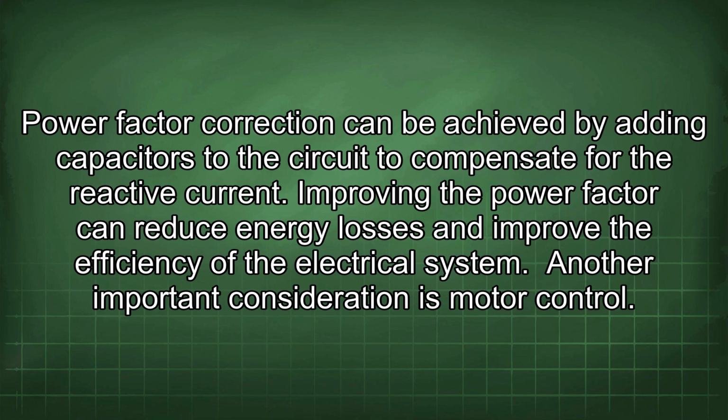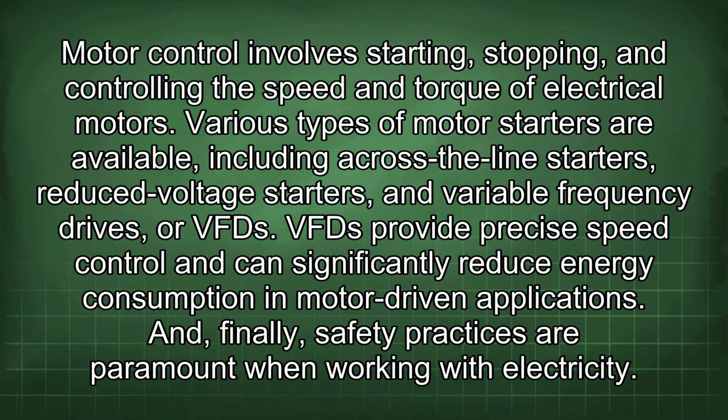Another important consideration is motor control. Motor control involves starting, stopping, and controlling the speed and torque of electrical motors. Various types of motor starters are available, including across-the-line starters, reduced voltage starters, and variable frequency drives, or VFDs. VFDs provide precise speed control and can significantly reduce energy consumption in motor-driven applications.